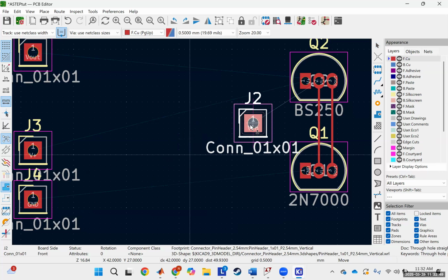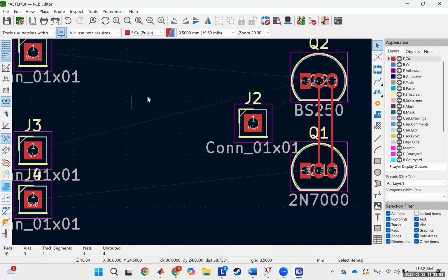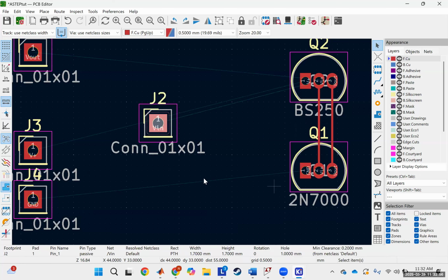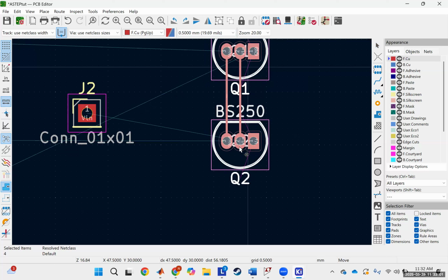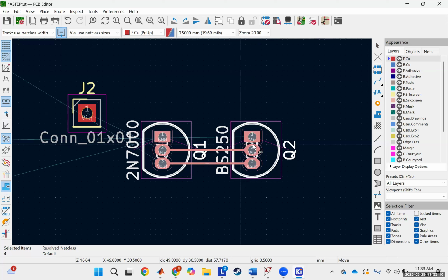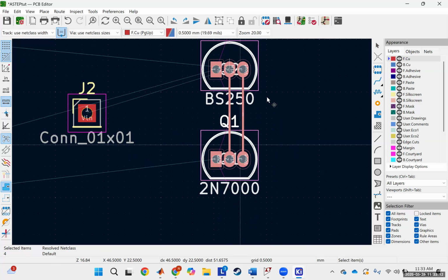You'll want to put this to the left of your transistor. Say if you put your transistors down the opposite way than I did, your VN would go on the other side. The main idea with these blue net strings, I think of them like spider webs. You don't want them to cross, because when you have crossing nets, you'll need something called a via to finish that route.